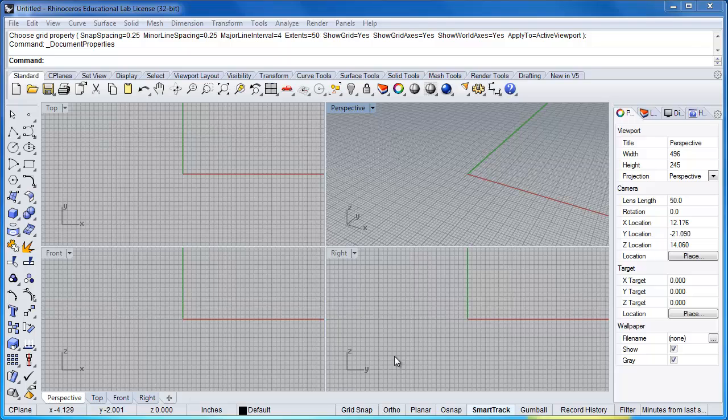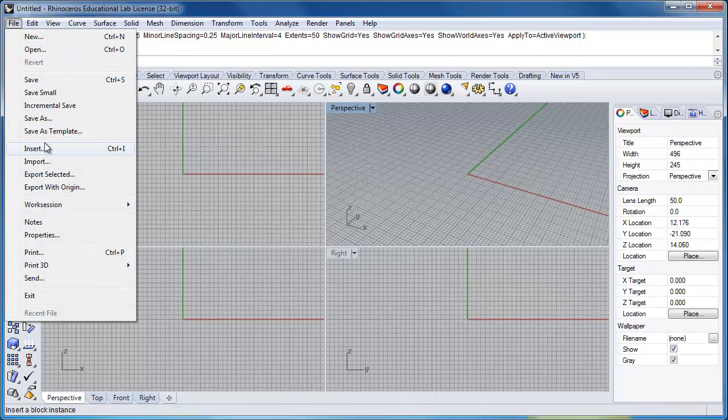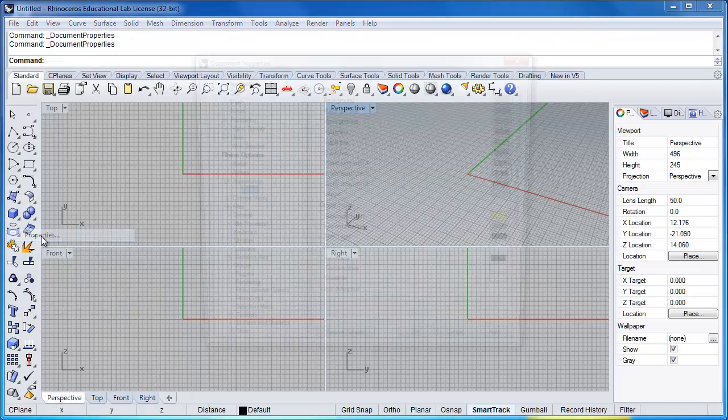Quickly to just go over some ways that you might improve the way that something prints, as I showed you in class. One of the things you can do is turn the background to white and get rid of the grid, and then you can do a screen capture or a print without the background. It's under File, Properties. On the Mac side, it's under Rhinoceros, and then Properties.